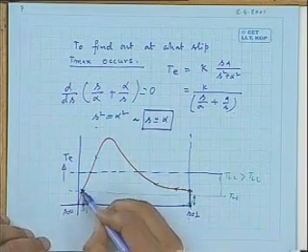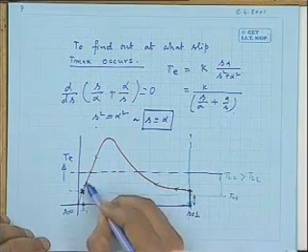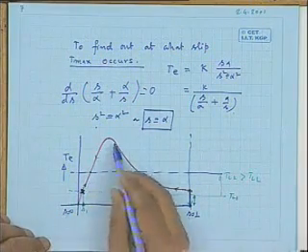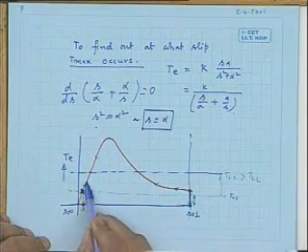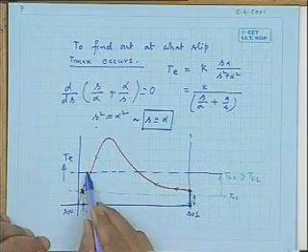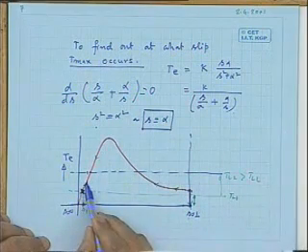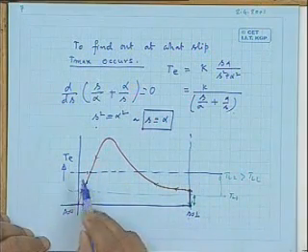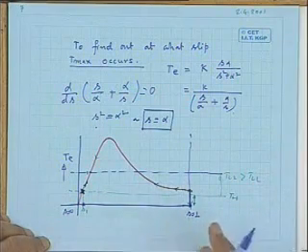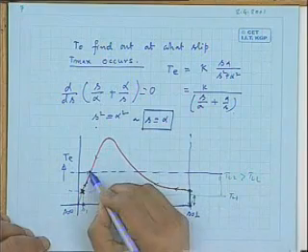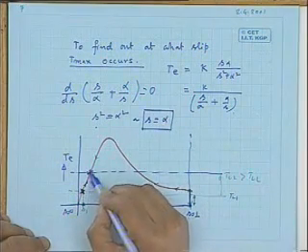Decelerate means the slip value will increase. That is, the operating point, which was here, will start moving towards the right. And at any intermediate point, if you see, you will find TL still greater than TE developed by the machine, and the machine will further decelerate. Is it not? Speed will further fall.